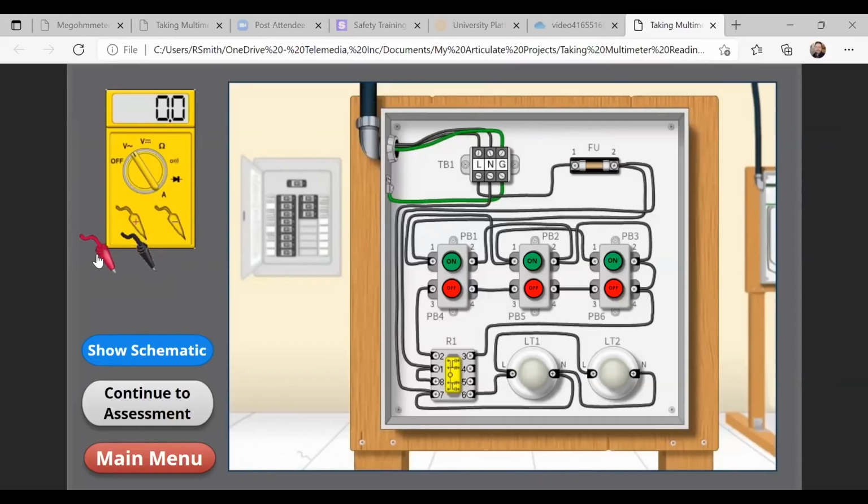One more example of measuring voltage is going to be from neutral to ground, right? So what should we expect in terms of voltage between the neutral, or what the National Electrical Code calls the grounded conductor, and the ground? Well, what should be received is, right here, neutral to ground, 0 volts. That's good. That means our neutral, our white wire in many cases, is directly connected to that ground. We want to see 0 voltage to ground.